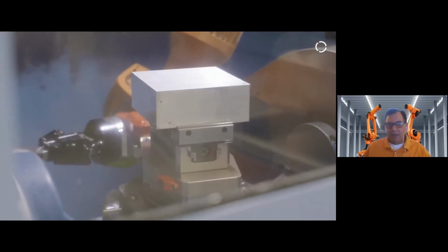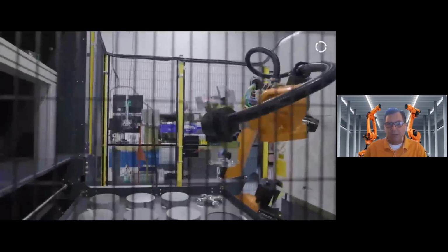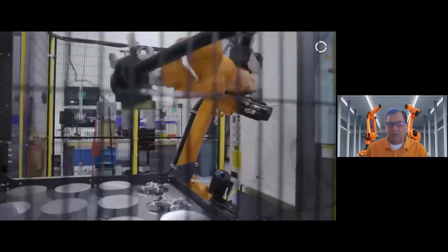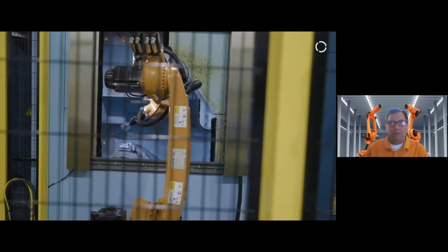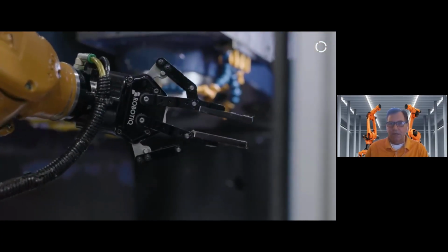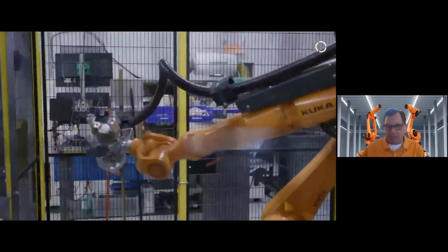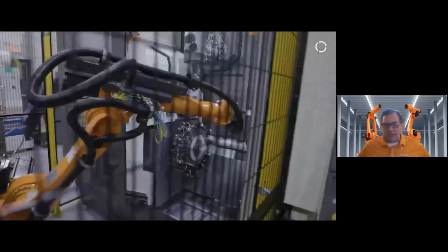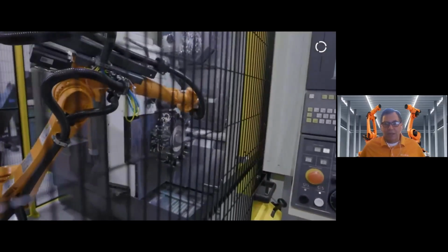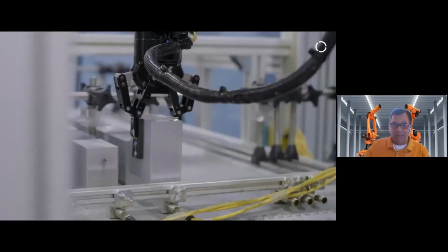Here's an example of a couple of grippers that would load raw materials, sometimes different size parts. Sometimes it could be finished parts, raw material. There's a gripper shown here that's actually servo controlled, so it can handle a variety of sizes of parts. That particular gripper there obviously is handling a round part. The other side of the gripper will handle the round part that's finished. So again, quite a variety of different gripper options available, depending on what your part looks like. But again, the more information you have on what you're doing today and in the future will be important for your solution.